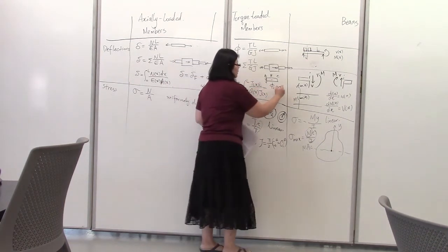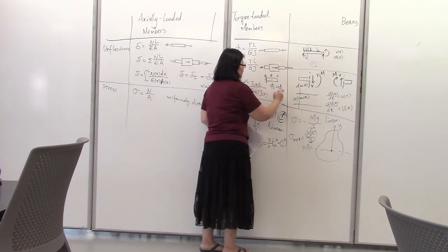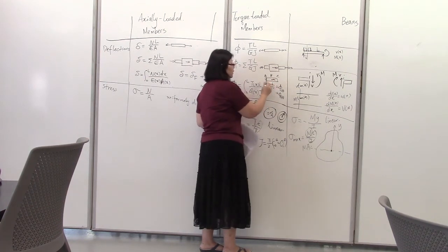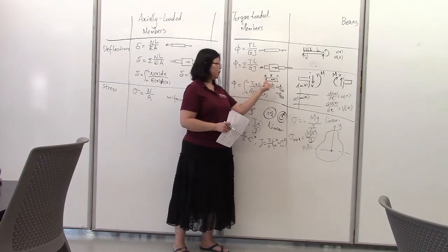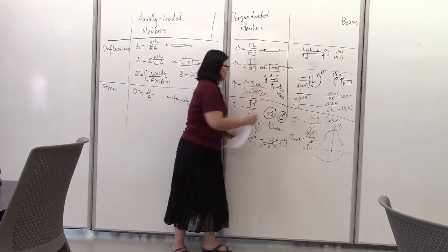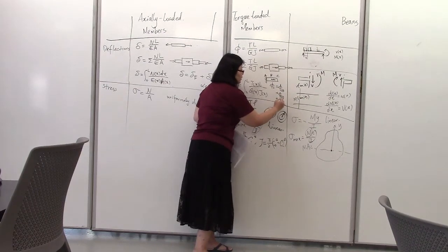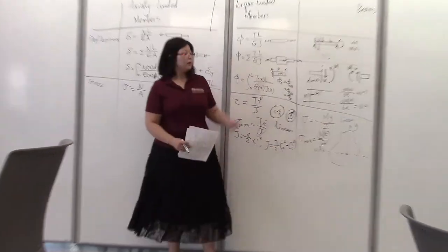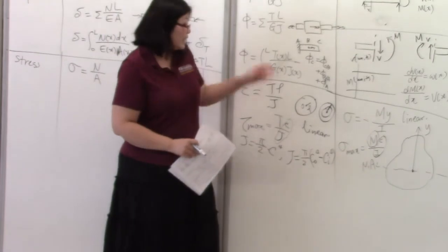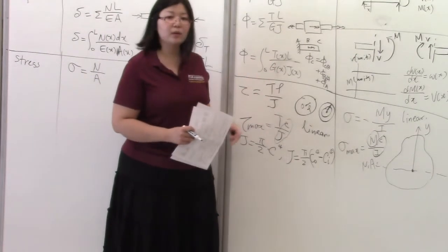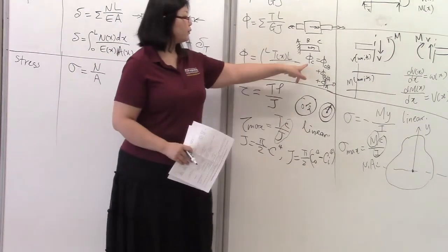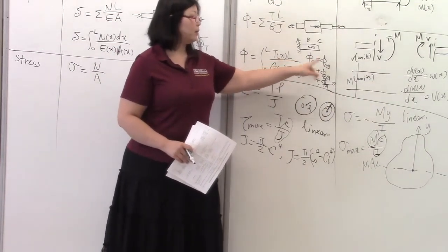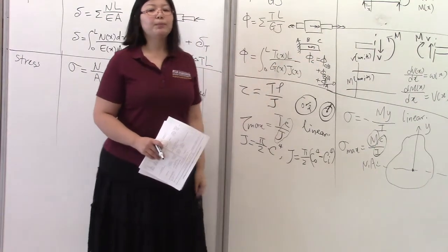So we use C relative to B and B relative to A if there is a torque applied or something such that B is a division point, then you divide the entire bar into 2 segments or something. So these relative measures plus the absolute rotation of the other end. Okay. In this special case, A is fixed to the wall, therefore you have 0 rotation there, and phi A is 0, so phi C just happens to be the algebraic sum of the 2 relative measures.